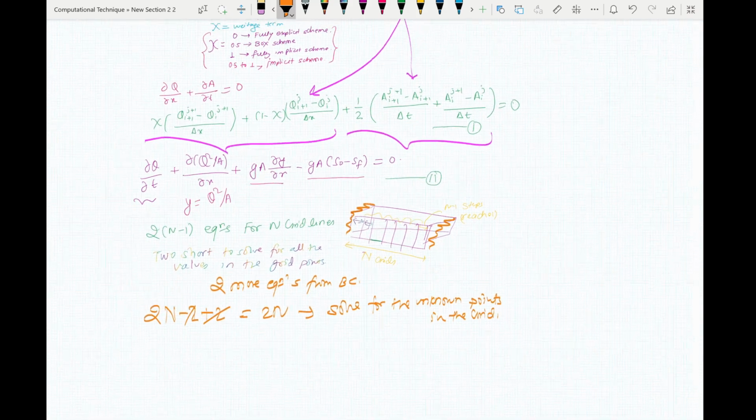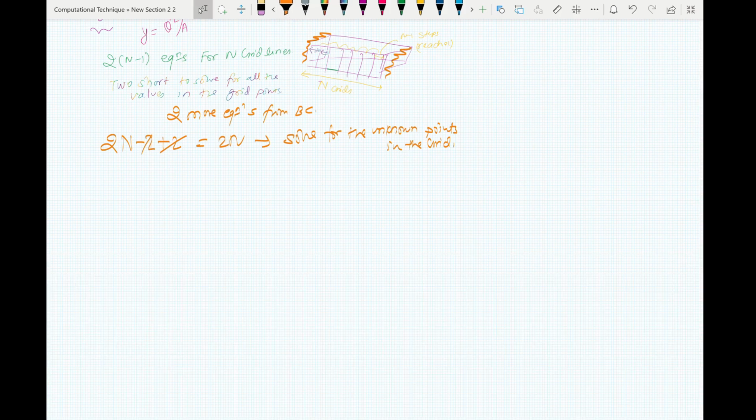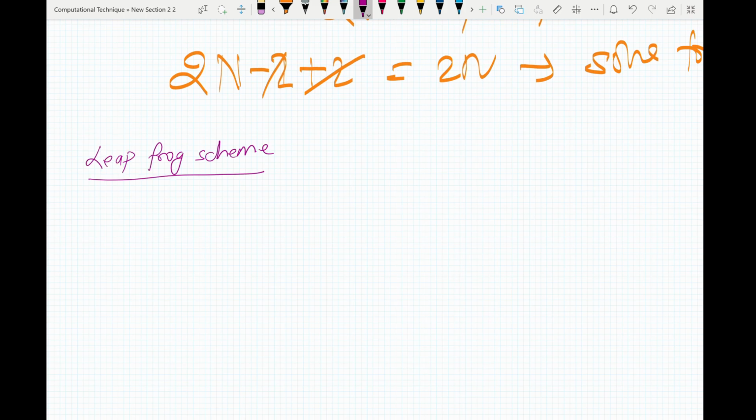Similarly, there is another scheme which is used for the dynamic wave model, which is known as the leapfrog method. What we do here is we use central difference approximation equations rather than using the forward or backward difference equations. Therefore, in this scheme we'll have three grid points: i-1, i, i+1, and j-1, j, and j+1.